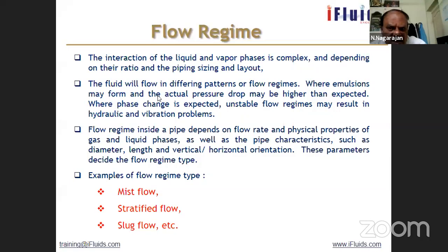Interestingly, if you notice at home, suppose you open the tap, sometimes you hear a lot of noise and then some gas comes. Suppose the line is empty. When you open it, what happens? The air in the line is first removed, correct? It is pushed by the liquid coming from the tank above, so the head in the tank drives the flow. If there is air entrapped inside the pipe, when you open the tap you will hear a lot of noise, then some gas comes out, then you will find pockets of liquid, and it takes some time to get a clear liquid flow. This is called slug.